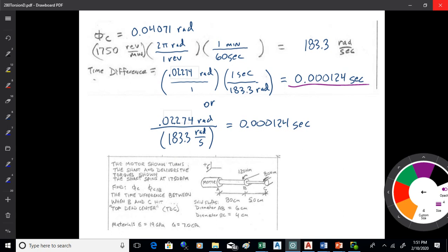Got any questions on that? Yes. For the directions with the right-hand rule, can you explain that? Yeah, right-hand rule, it's just a sign convention. Of course, it's used for moments in 2D. Counterclockwise is positive, clockwise is negative. What you do, like take that 80 Newton meters on the end. If you think of that in 3 dimensions, that shaft is kind of lying flat on the paper. Your fingers would wrap behind the paper, then come out the top of the paper and curl over. That's how you would represent that moment.